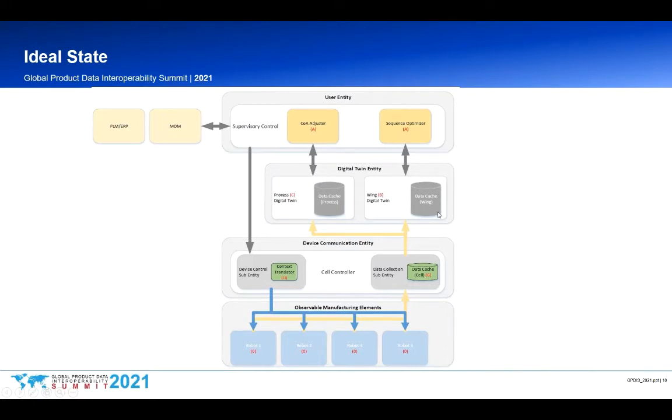And that information can be any number of things. It's going to tell us how they're executing their work, within the parameters of where a hole can be drilled, what it was actually drilled to, in that goalpost that we set from the CAD design. And if there are any hiccups or problems, it's going to tell us where it ran into them. And we're even going to give it the capacity, with sensors in place, that when, say, for some reason a part is unreconcilable and we blow the hole out too big, it's going to be able to stop the operation.